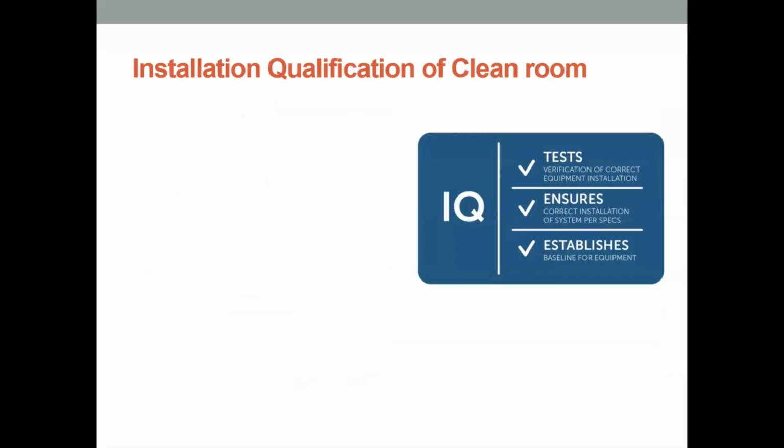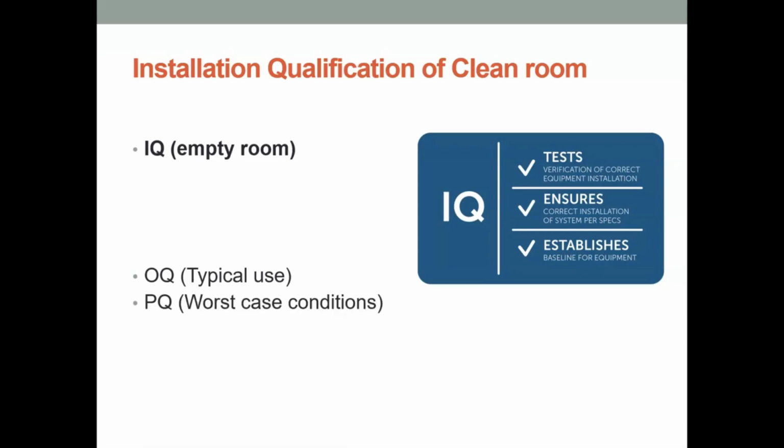So our installation qualification of a clean room. The IQ is going to be done on an empty room. In an OQ, we would be looking at the typical use of the room, and in a PQ, we'd be looking at the worst case conditions. But for the moment, we're only interested in the empty room and for the IQ.